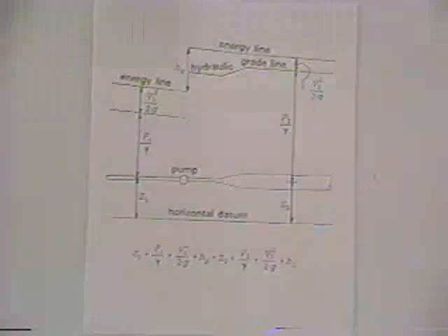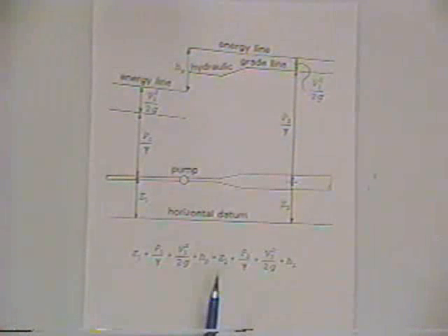And many of the problems that you solve is just a trade-off, as we said already, between the different forms of energy: the elevation head, the pressure head, the velocity head. And this illustrates some of the trade-offs, and it also illustrates that we can actually add energy to the fluid in the form of a pump. Head losses remove the energy, but we can also add energy in the form of a pump.